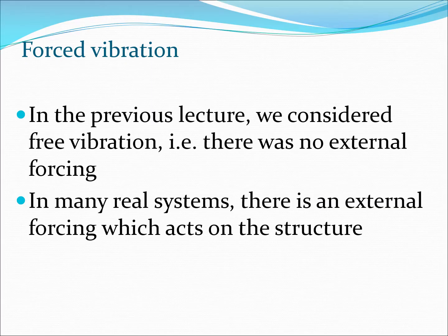So in the previous lecture on the spring mass damper system, and before that on the spring mass system, we basically neglected forcing. We assumed that there is no external forcing, and this is known as free vibration. Here the system is basically pulled from its baseline position and then released, and it moves on its own. Now free vibration gives you some basic ideas about some internal characteristics of the vibratory system, such as its natural frequency, its damped natural frequency, its response, and so on.